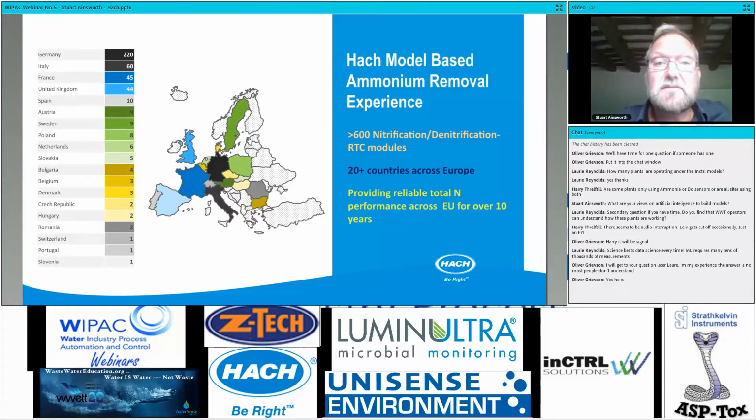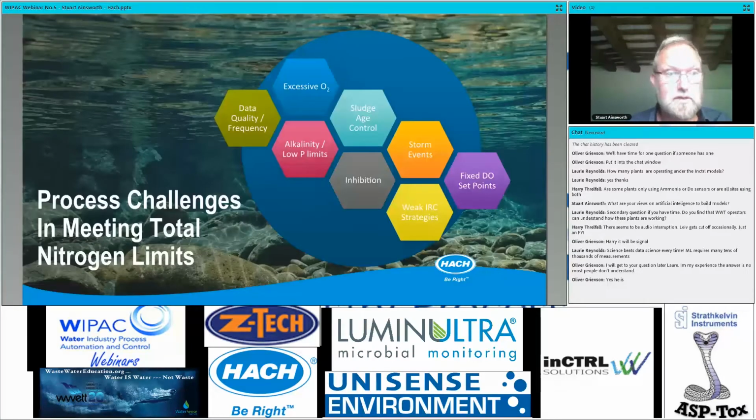And in a UK perspective, there's also low phosphorus on the horizon. So we think that the alkalinity recovery associated with denitrification is going to be an interesting story for the UK plants in the future, because obviously there are very few sensitive waters for total nitrogen around the UK, but I think alkalinity availability is going to become a much bigger story in the coming years.